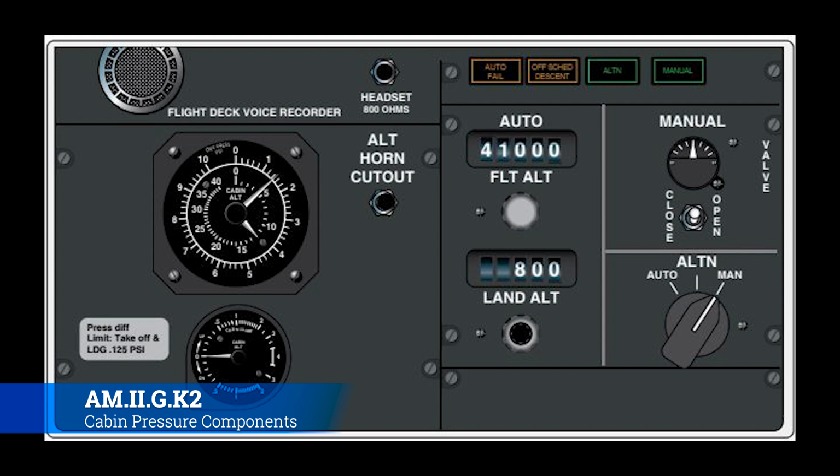But this is a way you could end up using this. If you're going to, you'll end up having to do what's called high blow or low blow. You probably won't ever do high blow unless you work at Boeing, because it's really dangerous. But low blow, you'll end up having to do. You have to test the pressurization system on board the aircraft to make sure that it's working correctly based on any kind of maintenance that you'll do. So you have to get familiar with this panel. But really, it's pretty easy to operate, and then the AMM is going to walk you through it, like Barney style. So you don't really have to worry too much about it. Just know that that's kind of a thing that you might end up having to do.